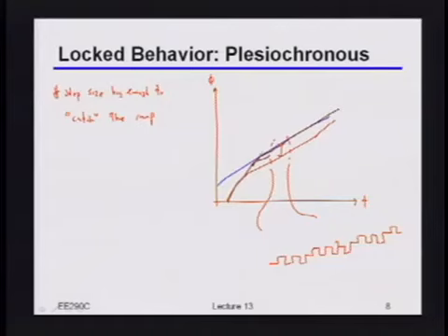Now, of course, there's still going to be the dither around there, but at least now the size of that dither is not set directly by the frequency error that you're tracking. Okay? You still have to make sure that you can keep up with that ramp. But the good news is that since we're only going after a few ppm, that's usually a pretty easy thing to do. Okay?